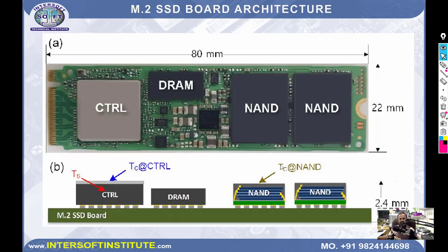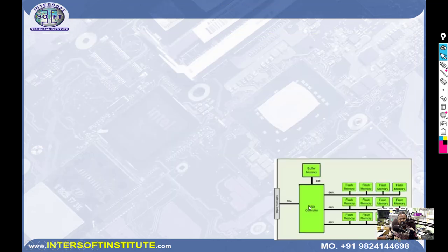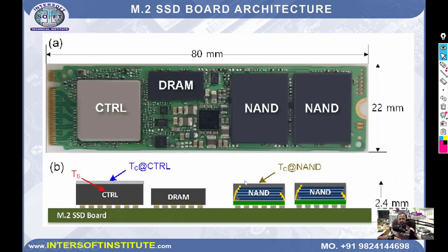In an SSD, there is one controller, and it controls the flash ROM with the help of a buffer. Sometimes the buffer comes inside the SSD controller, and nowadays flash and controller both are combined in one IC. So this is your controller. In older ones, RAM is there, controller ICs are there, and the NAND chips are there. They are all BGA components, soldered on the top, and the bottom has nothing.